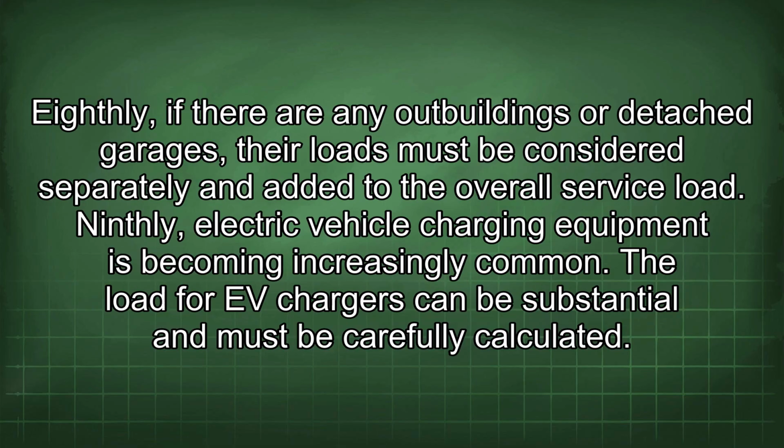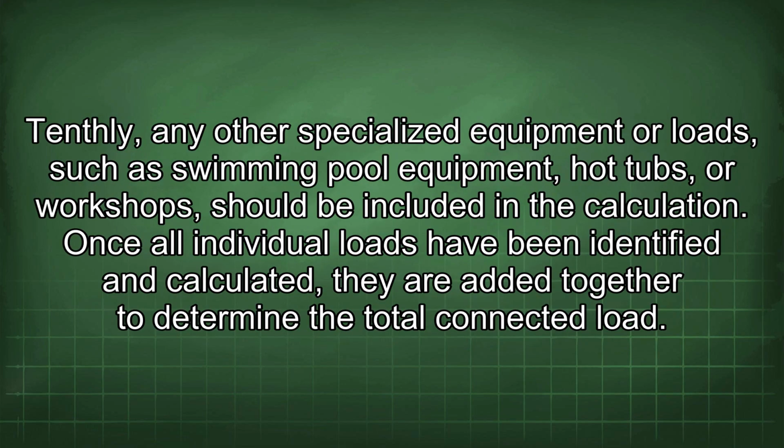Eighthly, if there are any outbuildings or detached garages, the loads must be considered separately and added to the overall service load. Ninthly, electric vehicle charging equipment is becoming increasingly common. The load for EV chargers can be substantial and must be carefully calculated. Tenthly, any other specialized equipment or loads, such as swimming pool equipment, hot tubs, or workshops, should be included in